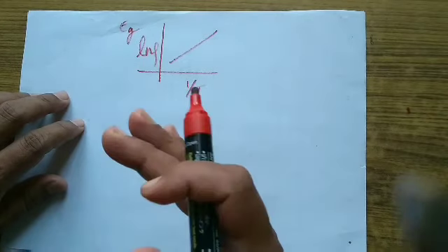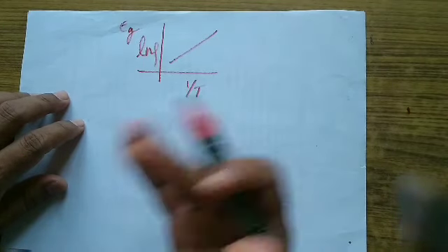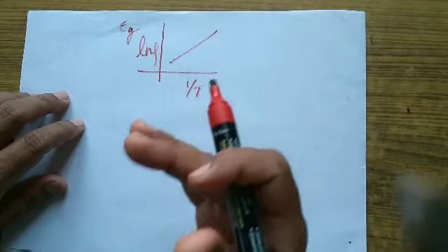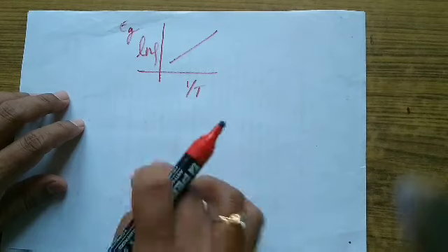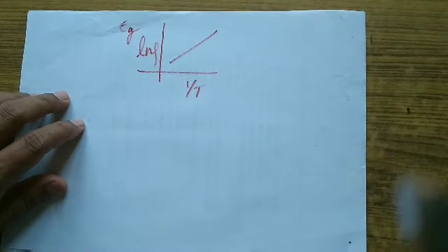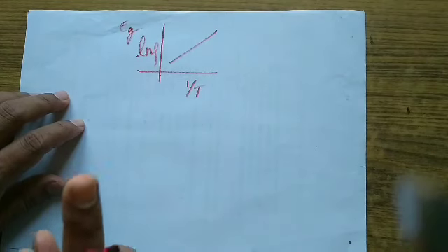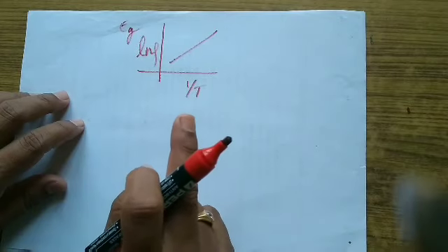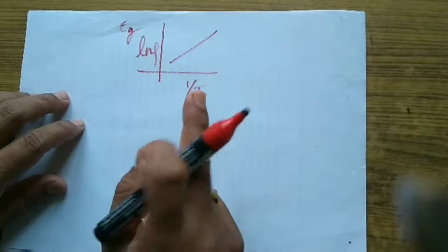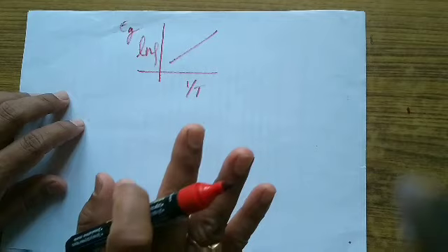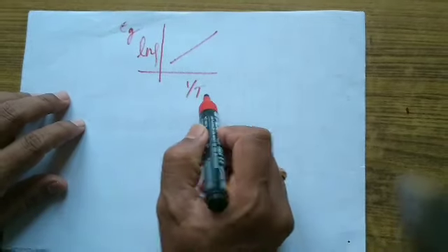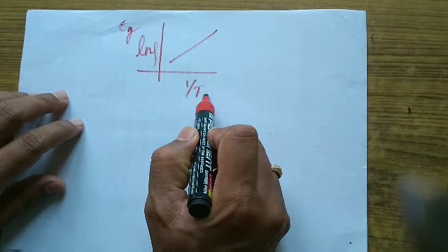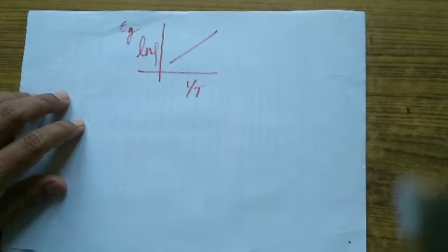Therefore, if you increase the temperature, due to thermal agitation and the scattering of those free electrons, resistivity increases. But here in a semiconductor, increasing temperature is creating free electrons, which leads to a decrease in electrical resistivity. That is the reason why the electrical resistivity is inversely proportional to absolute temperature.